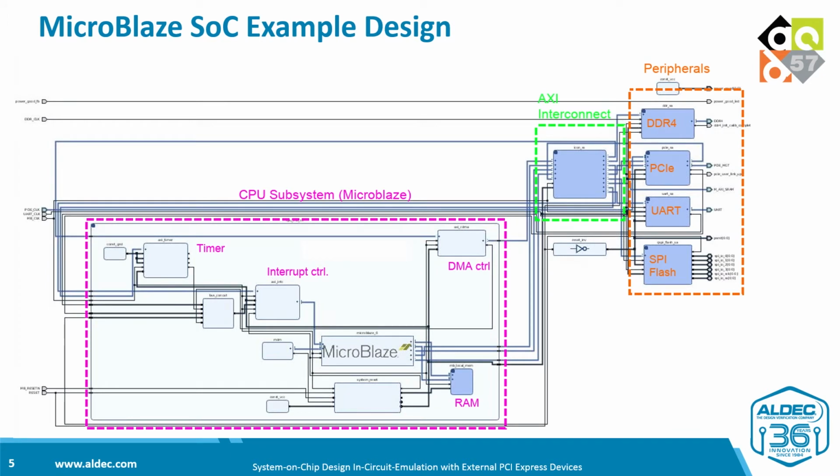So this is how the actual design block diagram looks like. We chose MicroBlaze for the simplicity of the design. With MicroBlaze, the entire design process could be done using Xilinx block diagram editor and ready-to-use IP cores from the library.